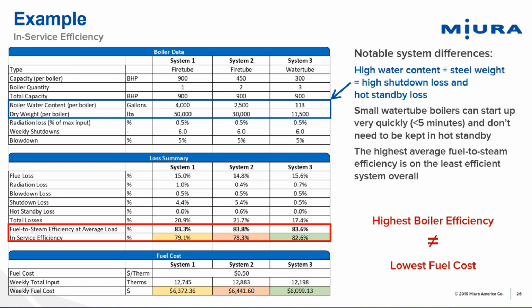Yeah, no, it's a good point though. The hot water boiler advertised efficiency will be much higher typically than a steam boiler. And there's a number of reasons for that, but the main reason is the fact that you can have it condensing, and you're not getting bad water quality within the hot water boiler because you're not actually having boiling occur. So you're not having cycling up occurring the same way as you do in a steam boiler.